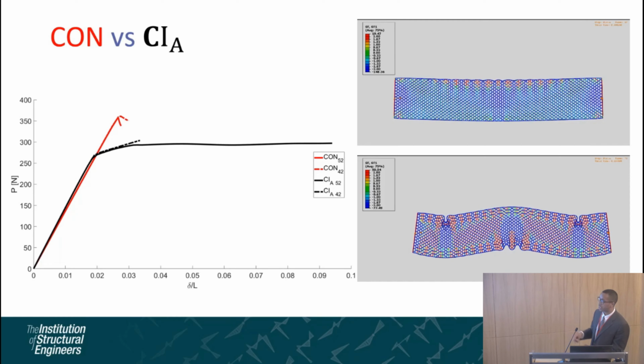In the bottom panel, you could actually see the plateau region has extended quite substantially, and this is because we're seeing some local effects at the top face and the bottom through the snaking behavior that you saw, and this led to local effects occurring at the top and the bottom face, and therefore much more end shortening and greater energy absorption capability.